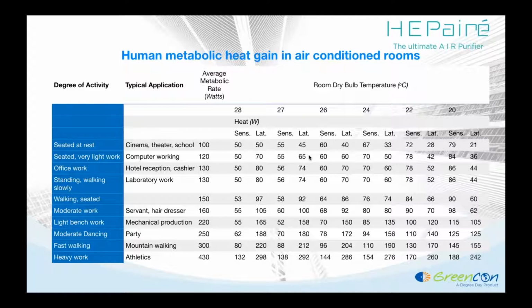So ideally, they are to be replaced, and for HEPA, for sure, they are to be replaced. In this kind of scenario, when you're talking of a clean environment where we are putting a HEPA, you can easily anticipate the life to be well over 2 to 3 years, and in an ideal scenario, it can go as high as 10 years also. So the cost of replacement is minimal, but the cost of not maintaining is something which could be your life also.